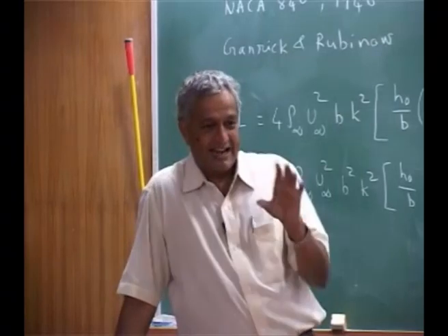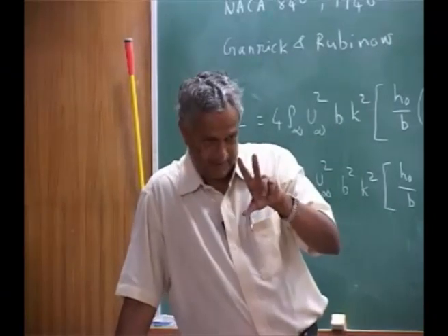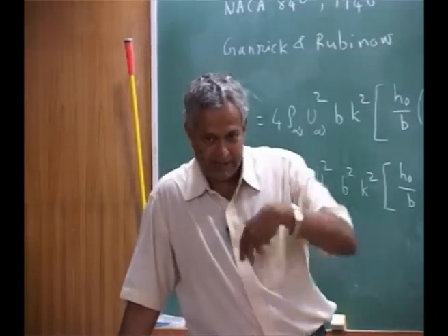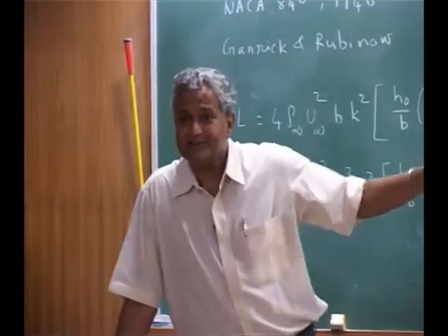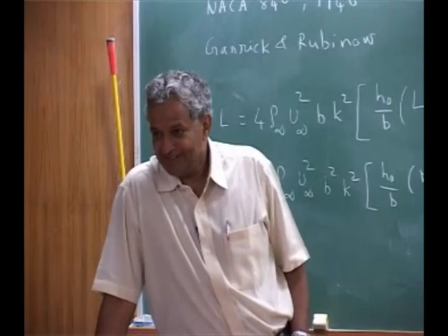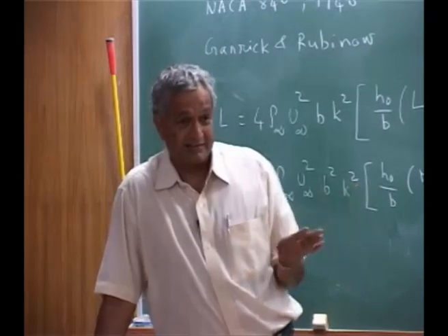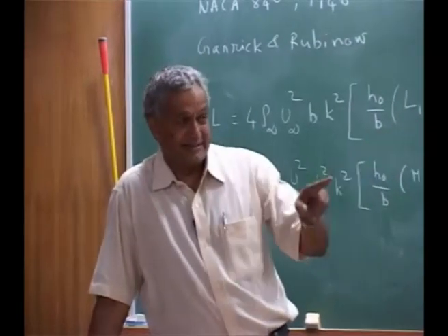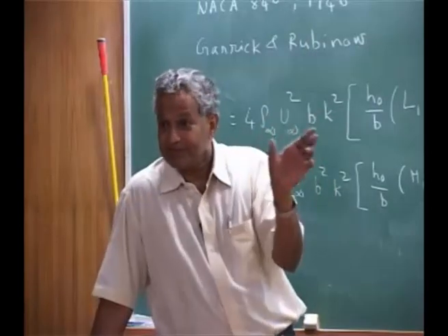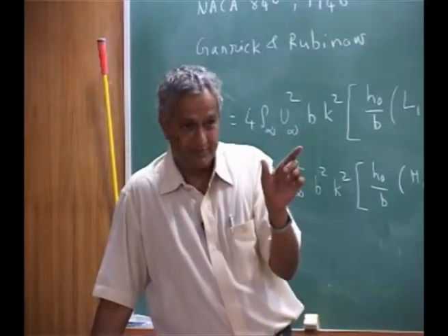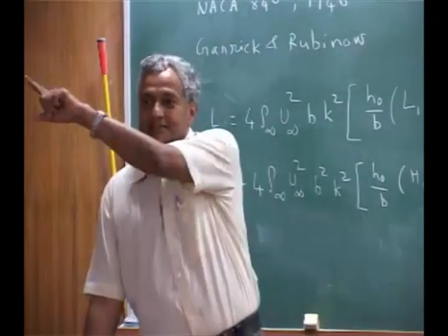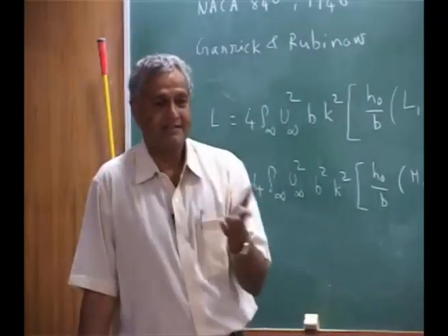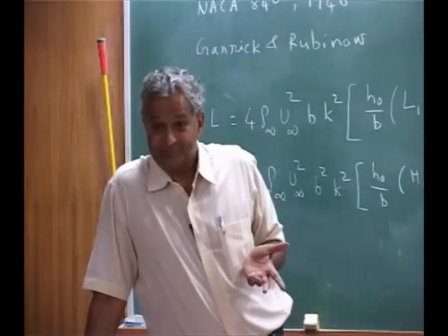And whenever your input value balances the damping force, you will find the resonance will come. That 90-degree phase shift will always be shown. When you draw the magnitude and the phase, you will find the phase curve will go like this. At resonance, the phase is 90 degrees.